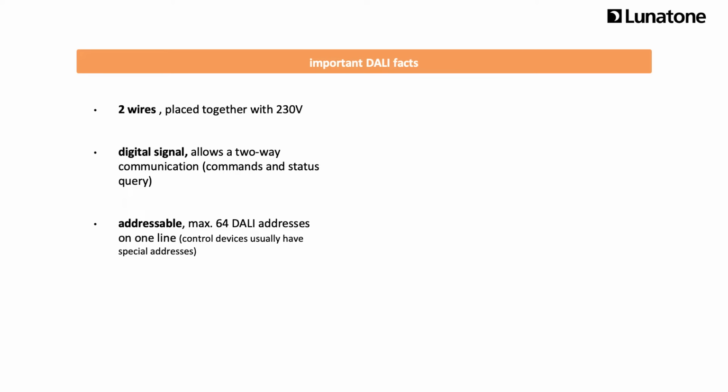The effective range of a DALI command is defined by the target address contained in the command. A distinction is made between individual address, group address, and broadcast. The DALI system supports up to 16 groups. Groups are used to control whole areas simultaneously. Each DALI device can be assigned to one or more groups. These groups can be adapted at any time without rewiring.